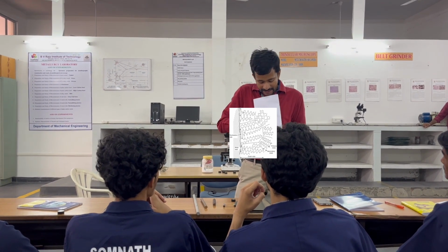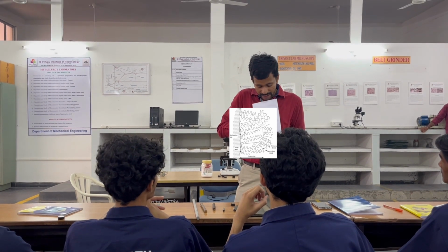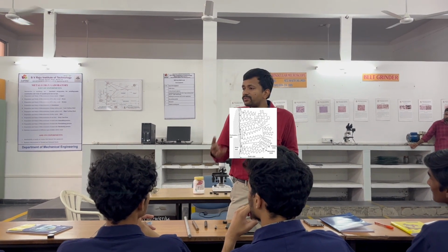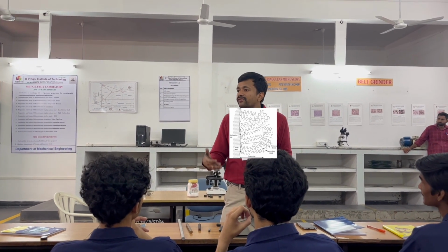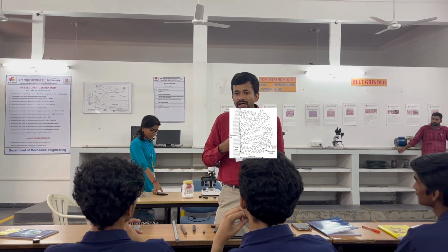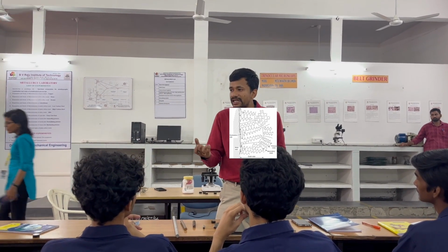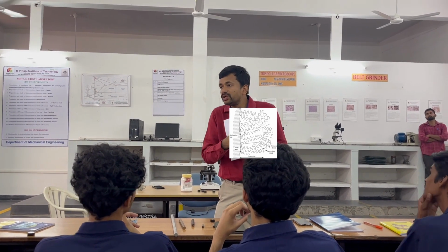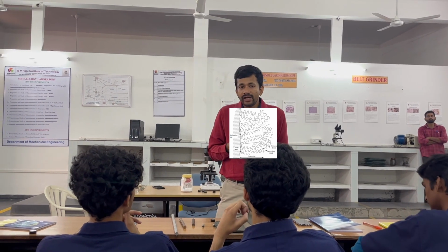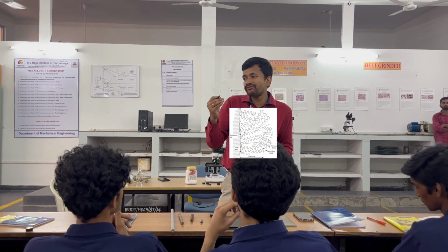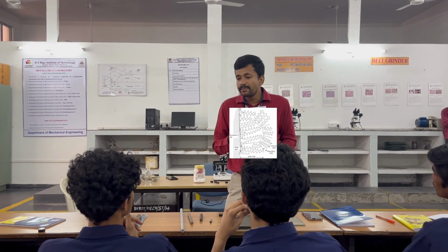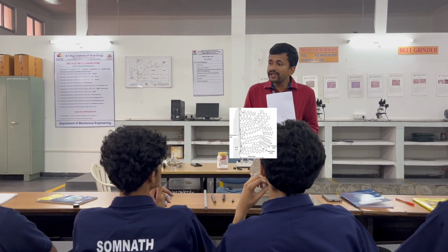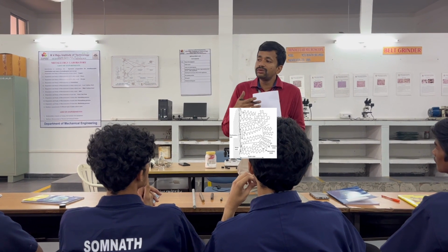So there will be many places where there will be nuclei and there will be growth in the form of a dendrite, right? And furthermore, as there is more stability, there will be more and more such nuclei and more and more dendrite formation. Okay, so this is the first stage, nuclei to dendrite formation. But still there is liquid. That means the temperature is still very hot, and everything will slowly transform into dendrites.